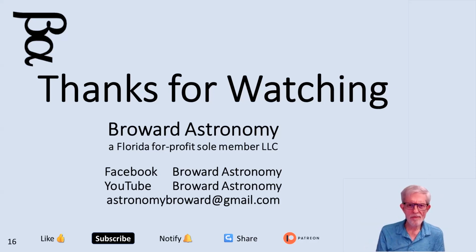And they'll talk about things like, if it gets closer than 50 miles from the station, they take this sort of action. Everybody get out of the station, go into one of the capsules, and then use the other capsule for navigating fuel. But they won't fire up the maneuvering Soyuz until it gets to like 25 miles. So at 50 miles, they just evacuate, move into a capsule in case their estimates are wrong. But if it gets within 20 miles, then they'll just boost it out of the way. They've done that. They've changed its position.